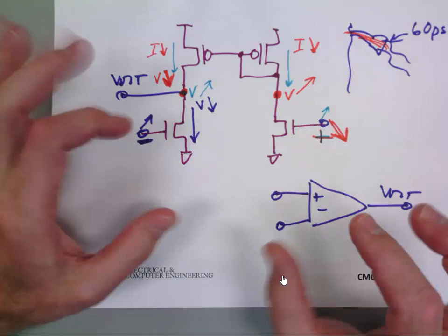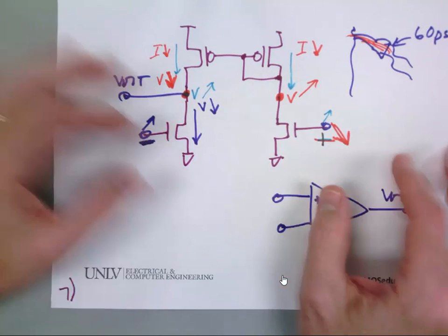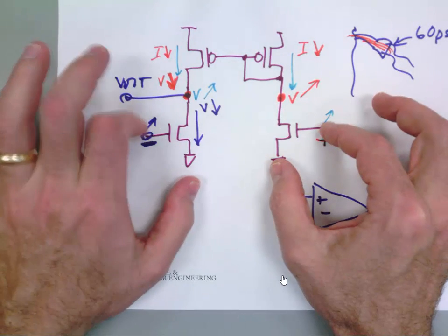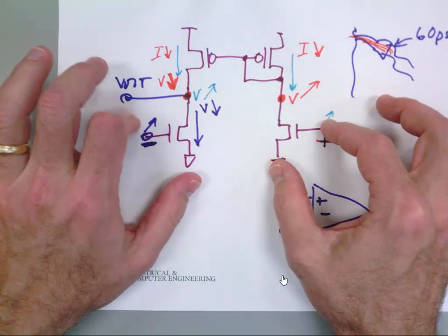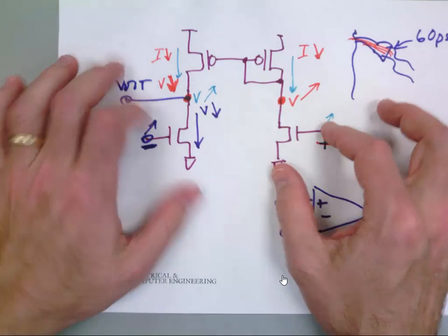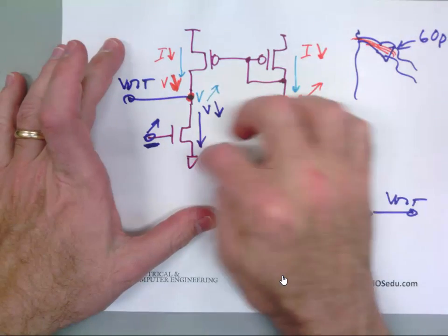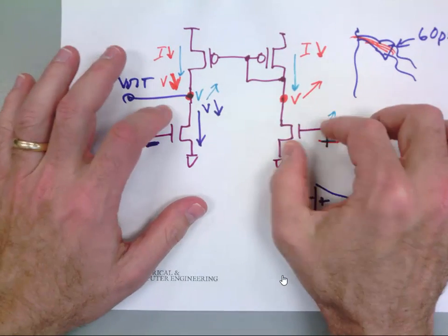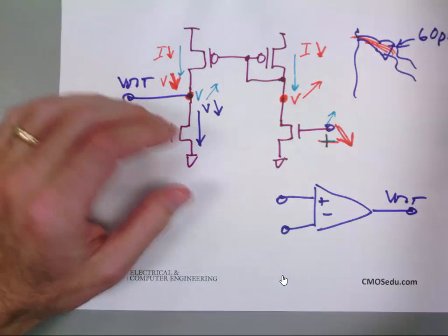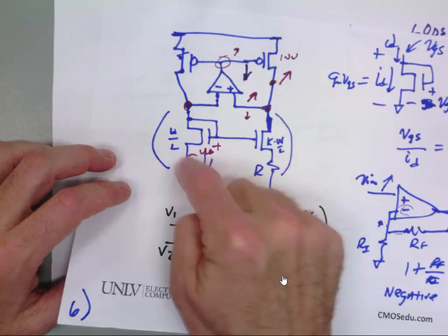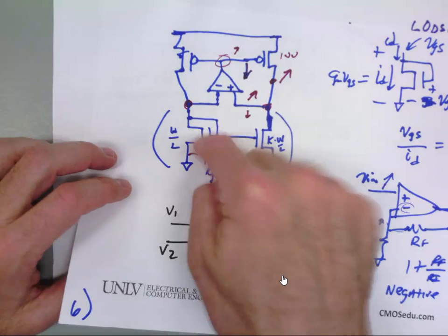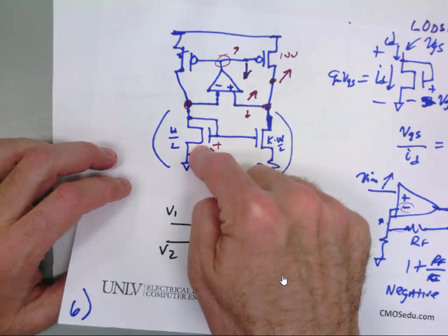The problem with this circuit in general design is these VGSs, the DC values, if you don't control them well, you're going to have crazy kinds of current flowing in there. And you can do a SIM and look at it yourself. It works fine in this application because the inputs are always at a VGS. So it just mirrors the current that flows in the beta multiplier.